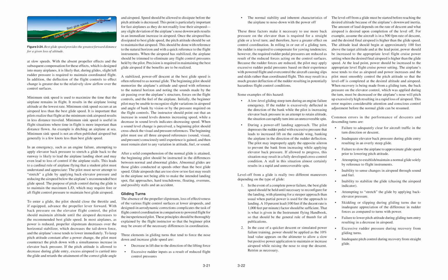Some examples of this hazard: a low-level gliding steep turn during an engine failure emergency. If the rudder is excessively deflected in the direction of the bank while the pilot is increasing elevator back pressure in an attempt to retain altitude, the situation can rapidly turn into an unrecoverable spin.